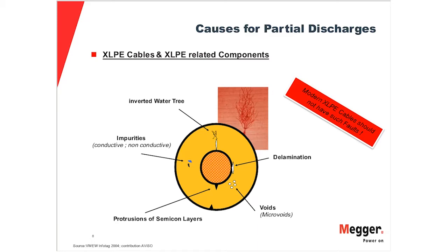The water trees are there from the very beginning, and they grow throughout the period of 10-15 years without causing any problem. The further they grow, the closer they come either to the conductor or to the sheath, which will then convert them from water trees to electrical trees. Once they are converted to electrical trees, we are able to measure them with partial discharge.